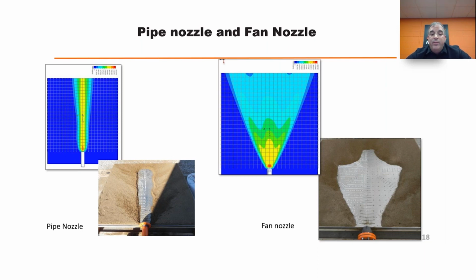However, as you can see from these photos, the pipe nozzle has a nice distance to it, but it's a very tight blast. It's not going to expand and clean walls like the fan nozzle, the one on the right-hand side. It will reduce the total force output, but it spreads out that blast, because mostly on vertical walls on a preheat tower, you're looking to clean that wall, and you're looking to maximize the amount of cleaning area that you can get out of that cannon.